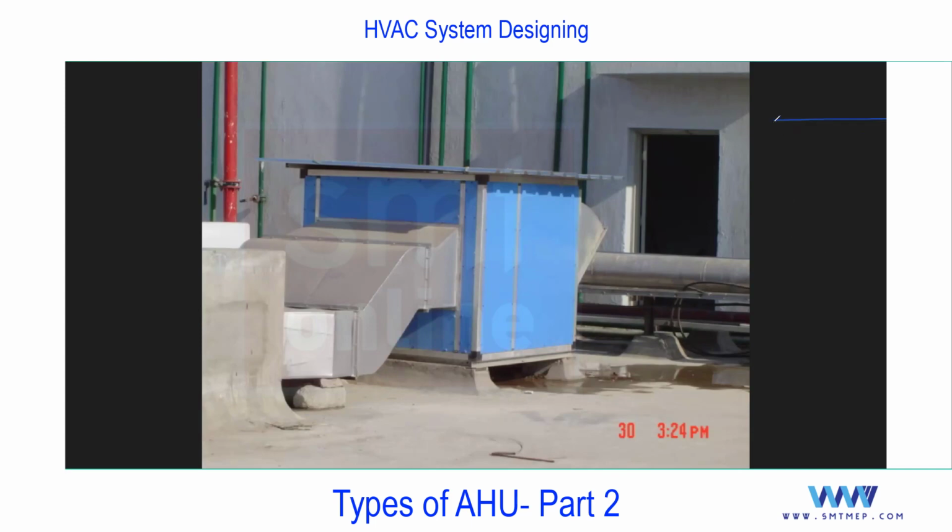For example, consider a floor, and in the previous session we discussed the VRF system. Assume one outdoor unit, connected to say cassette 1, cassette 2, cassette 3, cassette 4, and there are say 4 spaces. So how can we provide the fresh air? By using a separate FAHU. We place a separate unit, which can be connected to the chiller or to the condensing unit. It can be a DX system or chilled water system. And with the duct, we are providing the fresh air.